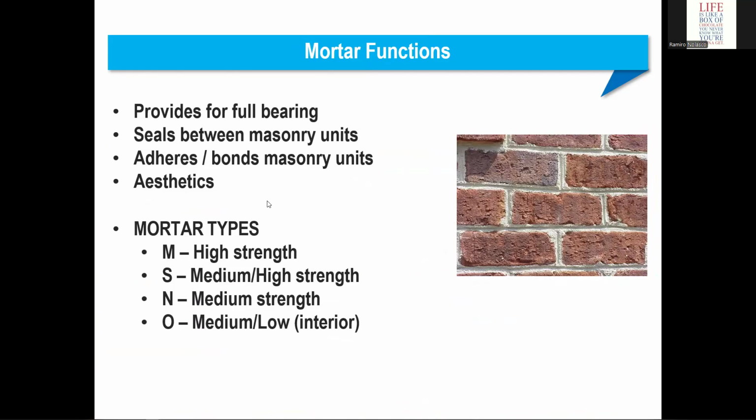So mortar function provides for full bearing, seals between the masonry units, also adheres and bonds the masonry units so they're connected, and for aesthetic purposes. So there are high strength, medium strength, and medium low for interior purposes.